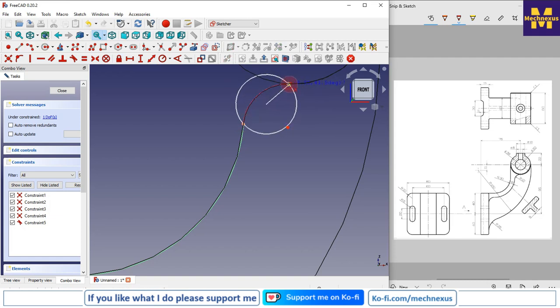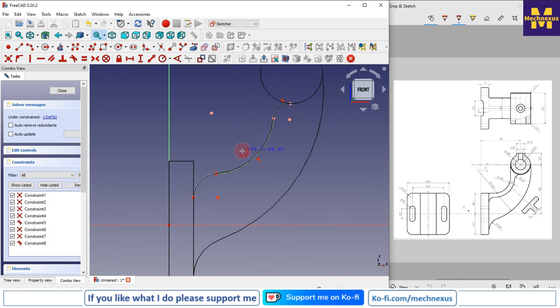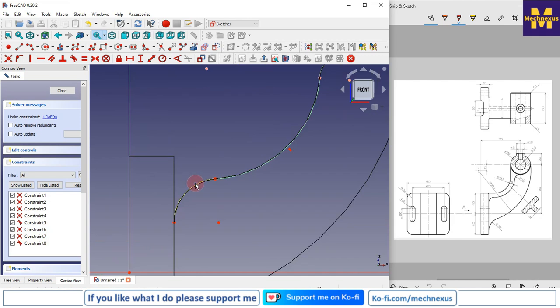So the trick here is that you just snap to it. So when it shows the tangency, just drop it. So it will automatically maintain the tangency. Now here it is not green. So select this point and this and click on merge.